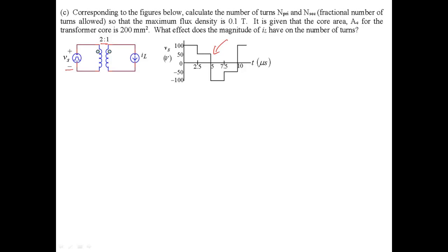I would use the definition of voltage rating for a winding that we introduced in the lecture. So V rating, I'll call this V primary rating. By definition, rating is the maximum positive volt seconds. Positive volt second is the product of voltage and time, divided by period.